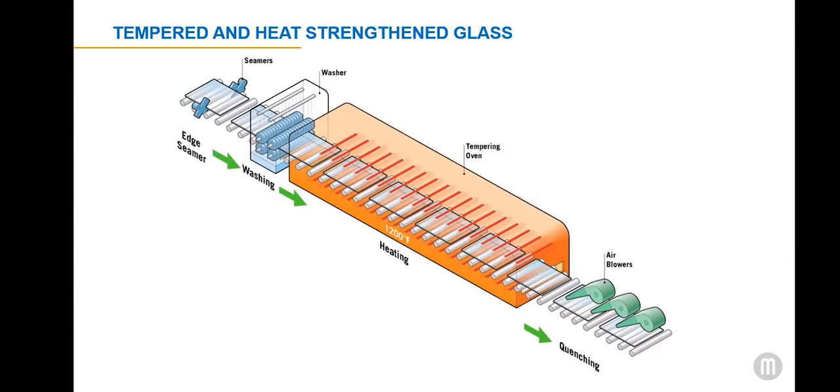Chemically strengthened glass is a type of glass that has increased glass strength as a result of a post-production chemical process. When it's broken, it still shatters into long pointed splinters similar to float glass. For this reason, it's not considered safety glass and must be laminated if safety glass is required. The chemical strengthening is a surface finishing process.